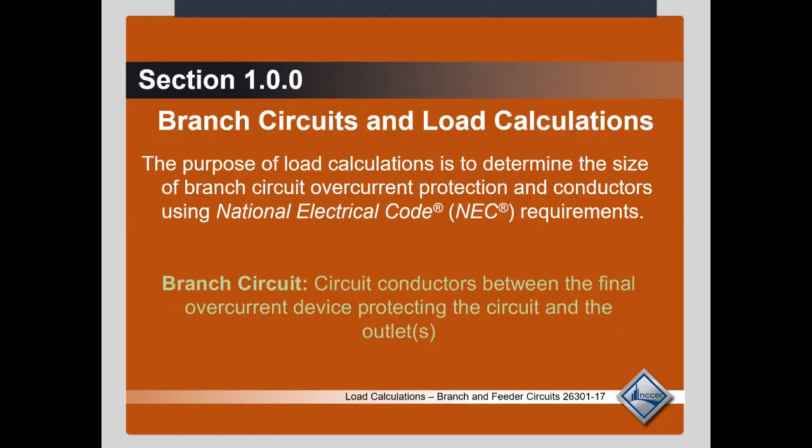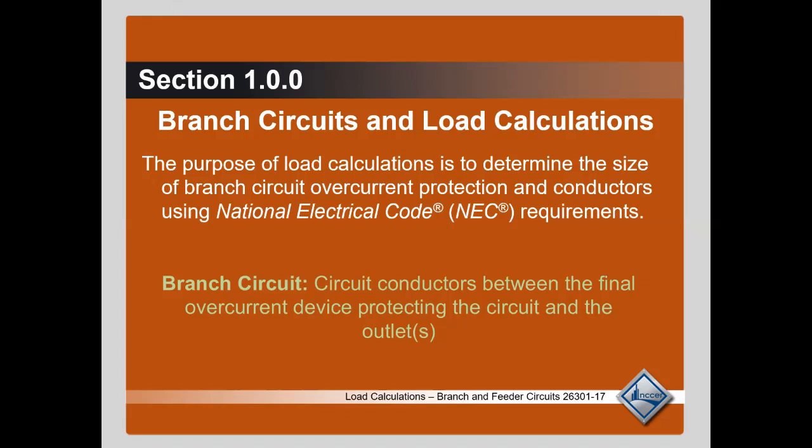So, all right. Branch circuits and load calculations of branch circuits using NEC requirements. So branch circuit conductors between the final breaker and the outlet. Okay. So that is the purpose of the branch circuits and load calculations. So you got your breaker, you got your outlet. Well, what is the demand load on that outlet? And that's going to determine what size wire we run, essentially.